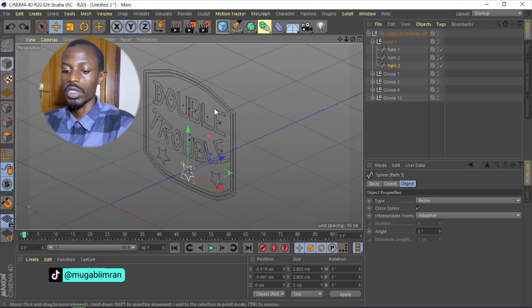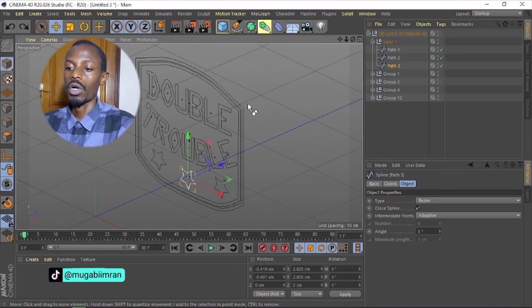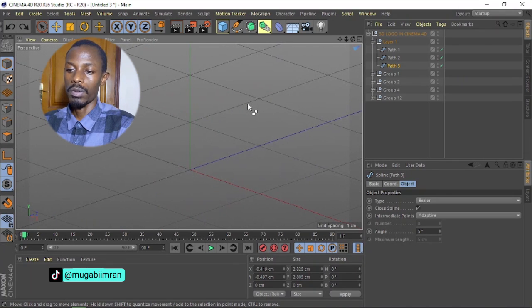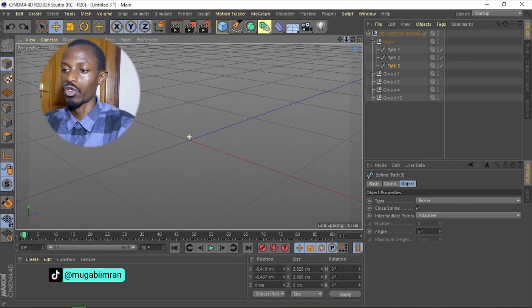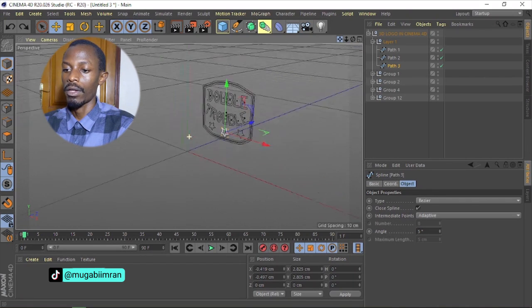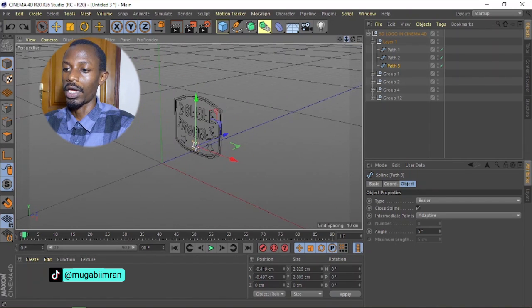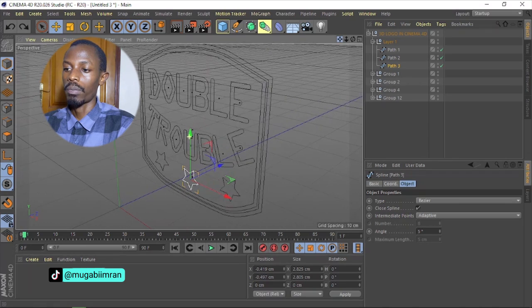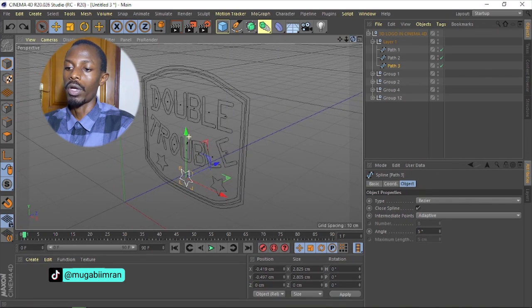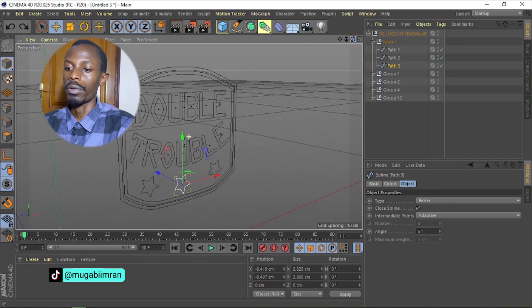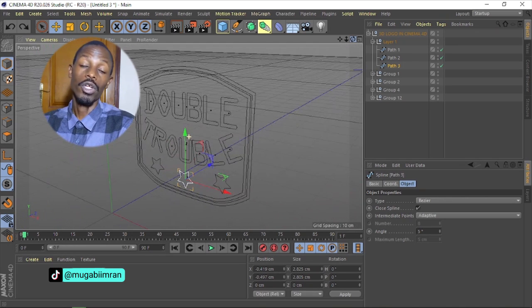So what you can do is use Ctrl+Shift+Z to undo all the camera moves. Okay, this will help us to go back to where we have been. So now we can zoom in slowly like this, and also use this button to move around. Zoom in again, and also place the logo into place, and maybe rotate around the logo a little bit like this using this button.